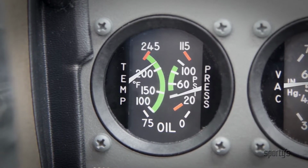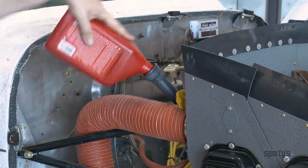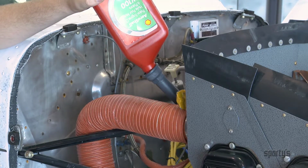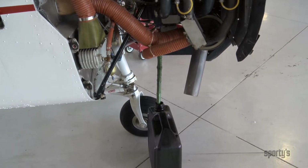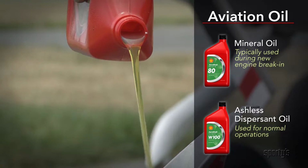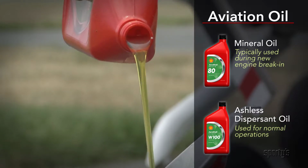There are 2 types of oil used in airplane reciprocating engines: straight mineral oil and ashless dispersant oil. A dispersant oil contains an additive that suspends contaminants, such as carbon, lead compounds, and dirt. This allows them to be filtered out or drained with the oil rather than deposited within the engine. This type of oil keeps foreign particles in solution without the disadvantages of ash-forming detergent additives.